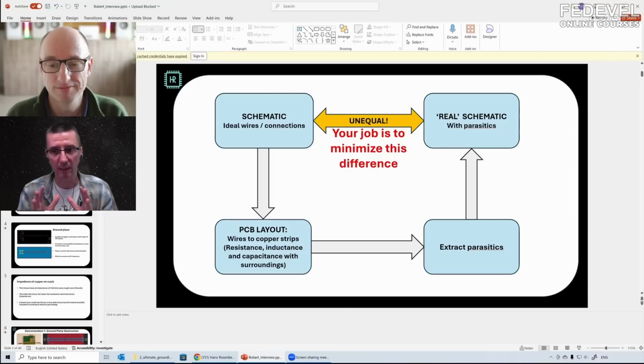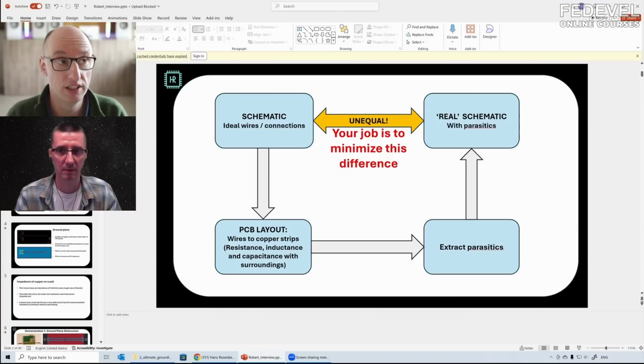And so in your board, you will have also the higher frequencies. If you are not aware what is going to happen with these higher frequencies, then that's exactly what can cause the problems. Yeah, exactly. I mean, if you have a gate that's capable of processing 400 megahertz and you put 10 kilohertz on there, it'll produce harmonics probably up to 400 megahertz basically. So yeah, there's a lot more interference than you think.